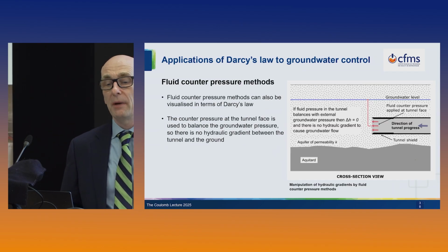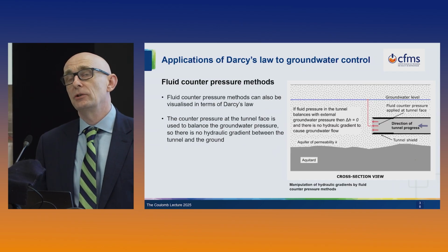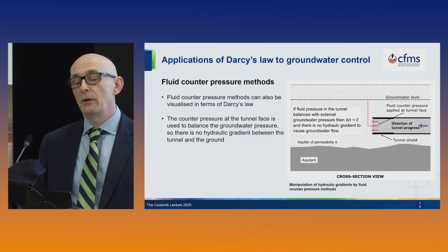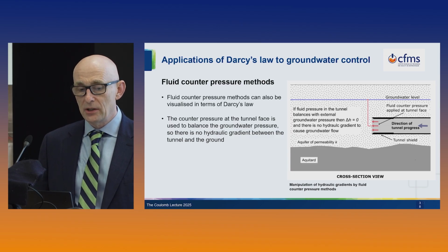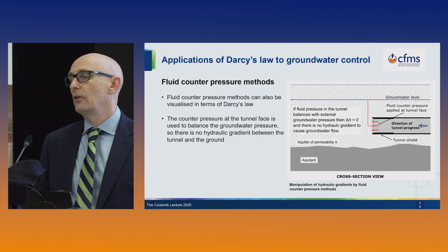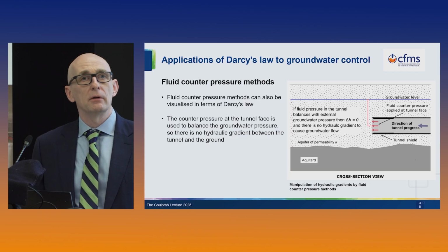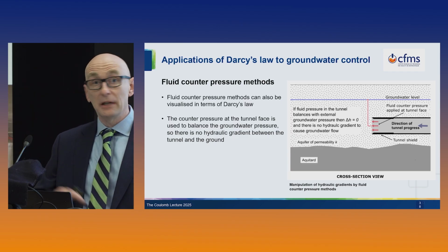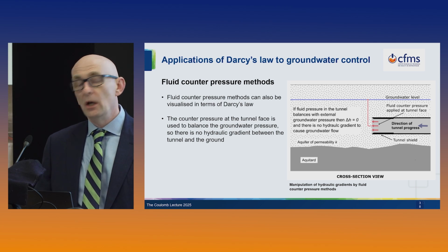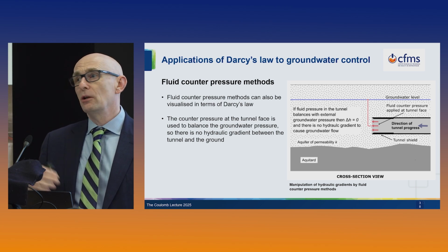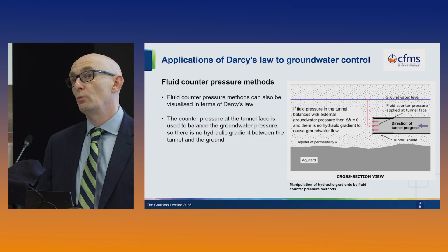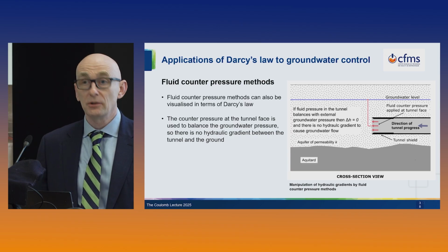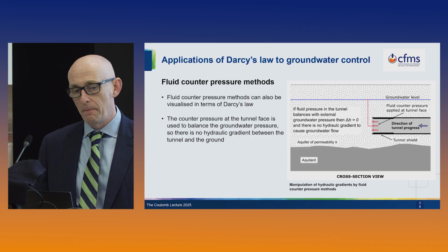For the fluid counterpressure methods, again, Darcy's law tells us what's going on. Because the point of the fluid counterpressure methods is that we are trying to balance the groundwater pressure with the pressure inside the excavation, so therefore delta H is 0, and if you go to Darcy's law, if delta H is 0, there's going to be no flow. So I would suggest that Darcy's law is a much more powerful tool than we currently give it credit for, because it lets us understand quite a lot of complex scenarios.